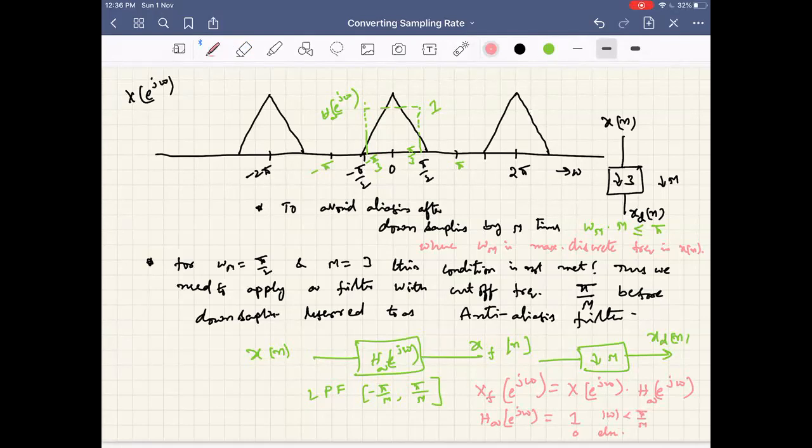Whatever we define here, please note that these definitions are from minus pi to pi range only, because the discrete time Fourier transform spectrum anyway is periodic with 2 pi. So we don't bother to define in rest of the region. Now let us sketch the sample spectrum in minus pi to pi range.